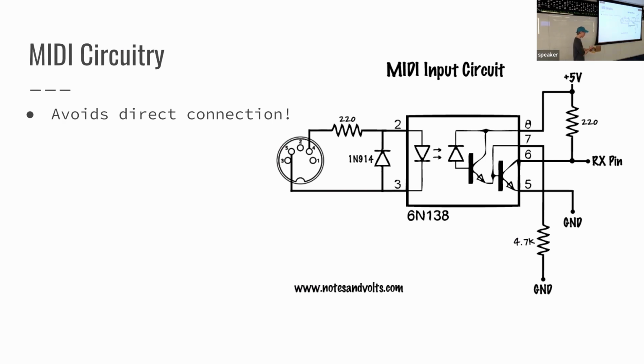Because we definitely have different power supplies and ground references, so if you just make a direct electrical connection between them, you'll end up with a ground loop, and you'll be playing audio back and you'll just have this hum the whole time. So we need to get that digital data from point A to point B without plugging it in directly.